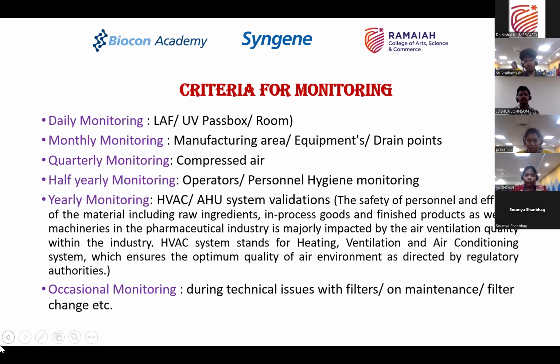laminar airflow hoods or clean rooms will be maintained with all the air pressure and air velocity. When the product is getting transferred from one clean room to another clean room, the passage, which is called the UV pass box, should also be monitored on a regular basis. So daily monitoring is required. Otherwise, there are chances of contamination during the transportation.